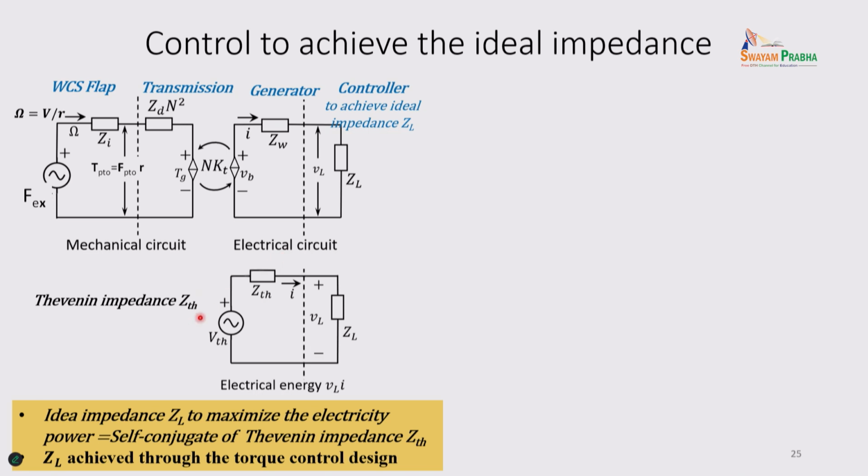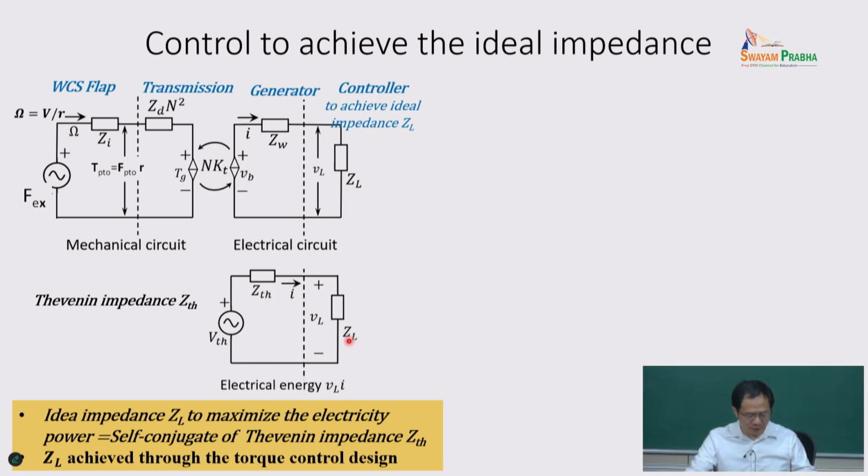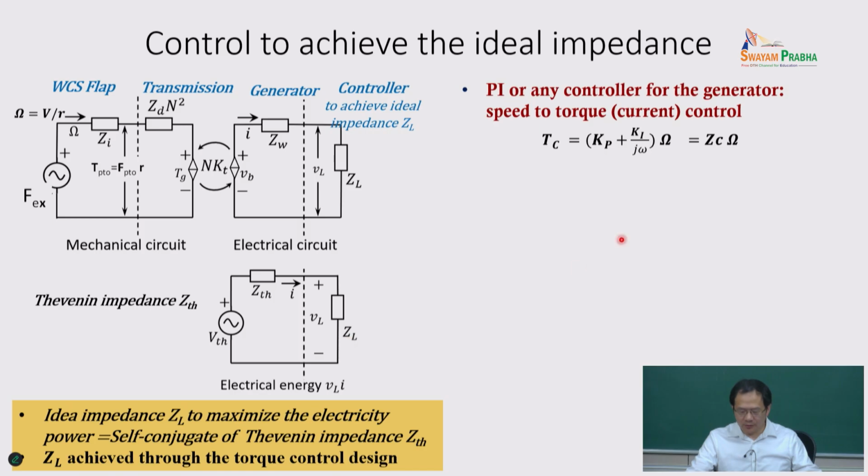If this voltage is constant, you consider the impedance a resistor, and you match the two resistors. Now, if you use AC voltage, there's a real part and an imaginary part. Then when you want to maximize, you have the complex conjugate, right? We highlight this again and again. Have the complex conjugate.